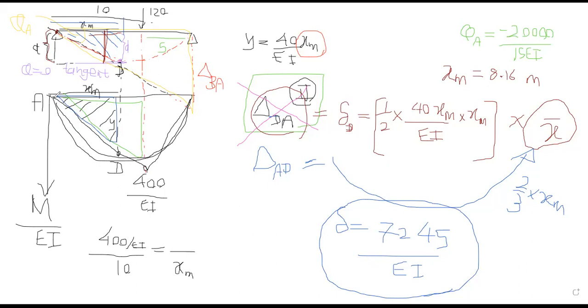But here's how it's done, right? Just consider if your load is somewhere other than the middle. Your maximum bending moment is just at that loading point, but the maximum deflection point is not, right? Okay, thank you very much.